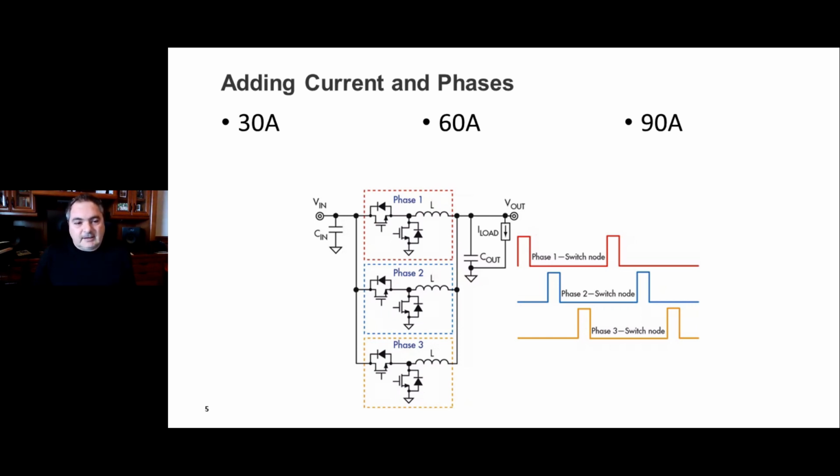But the rule of thumb that I've always used is for every 25 to 35 amps that you need delivered into a chip, I averaged it out, split the difference, and called it 30 amps. For every 30 amps of current you need into a device, you need to add a phase. So this is known good technology, right?